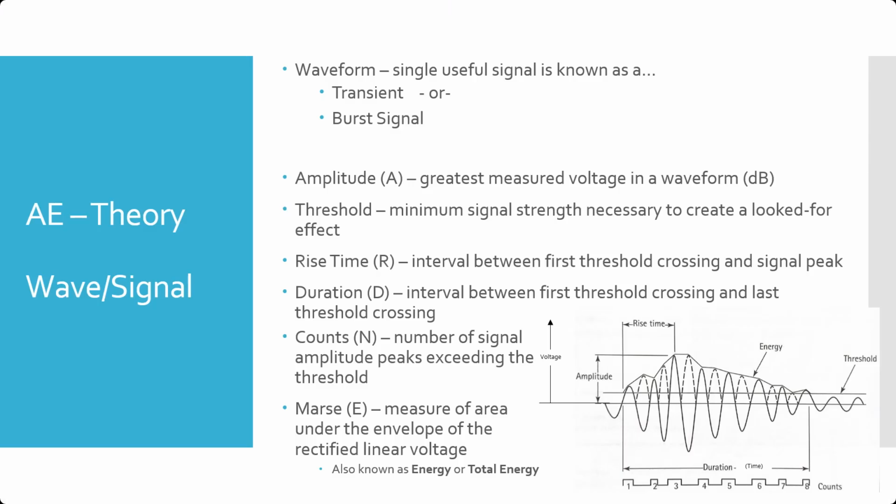And the amplitude is the greatest measured, say, voltage. Remember, we're looking at this from an electrical standpoint because we're taking that sound signal and sensing it using a piezoelectric receiver. And that piezoelectric receiver puts out an electrical signal, a voltage change that corresponds directly to the physical vibration that is hitting that piezoelectric crystal.